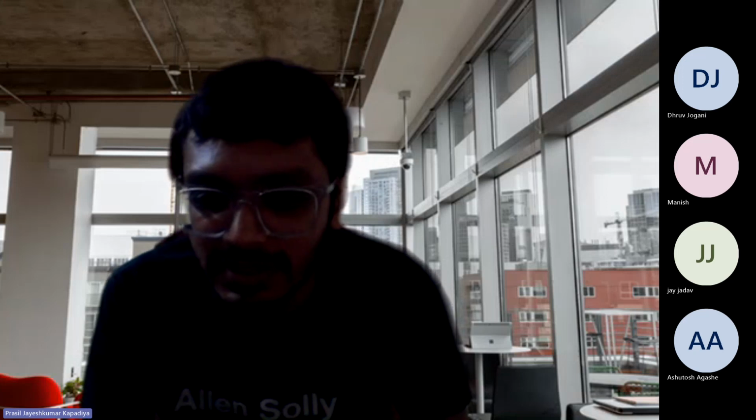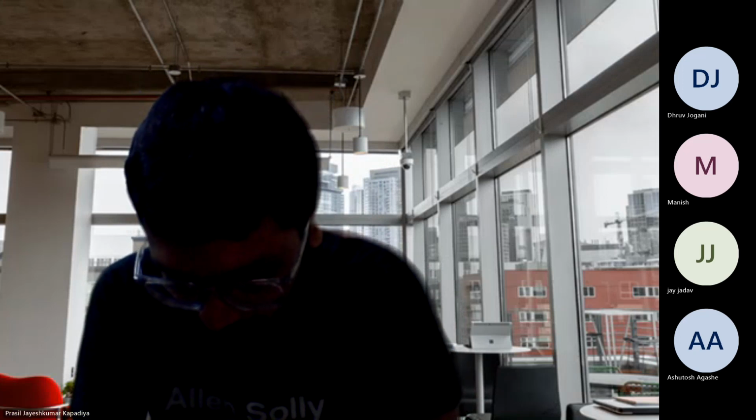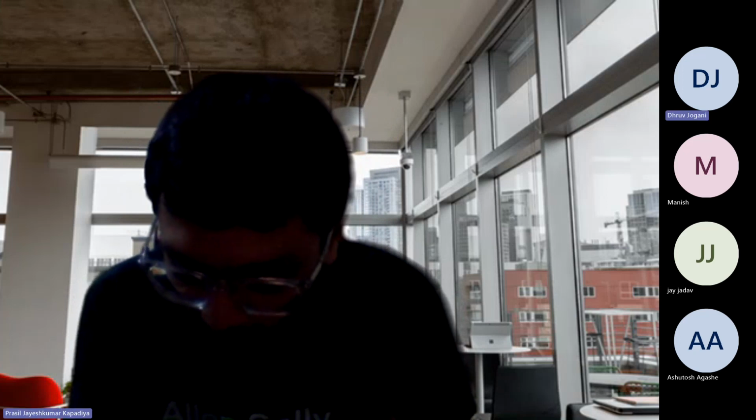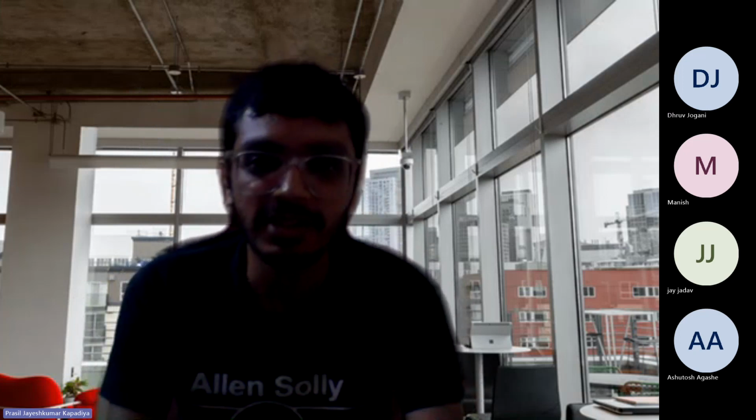So you're getting an error because of the design specification. What is the maximum mass fraction you are getting from there? Sir, the maximum I'm getting is 0.972 at 51 degrees Celsius of flash temperature. Okay, then leave it. The problem is anyway at its best.